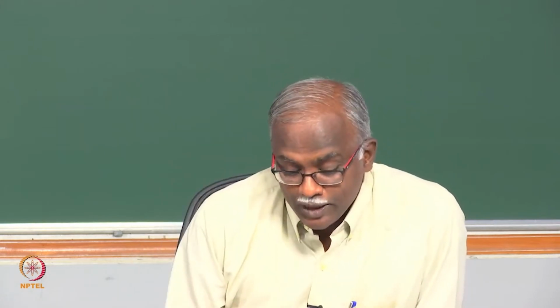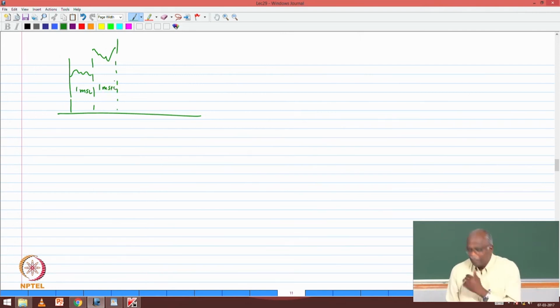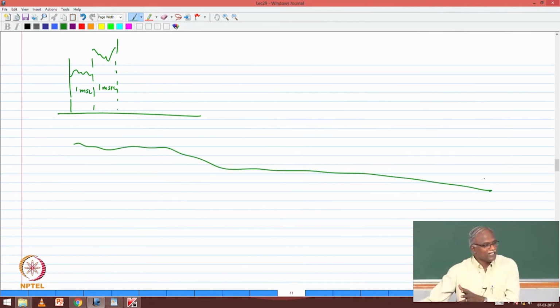Okay. So, what am I expecting from you? A fading pattern that lasts 1 millisecond, and then the next millisecond, because of hopping, it's a different channel altogether. The next 1 millisecond, I'm telling you, I want to simulate a frequency hop system. What will you tell me? Sorry, I'll give you 1,350 milliseconds of this thing. You throw away 1,349 milliseconds and keep 1 millisecond. So, you see that there is a lot of wastage in the computation that we are doing.